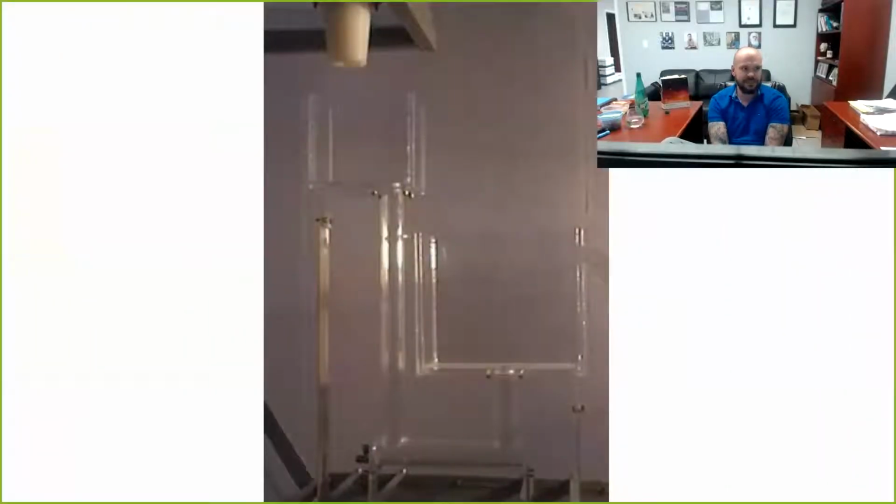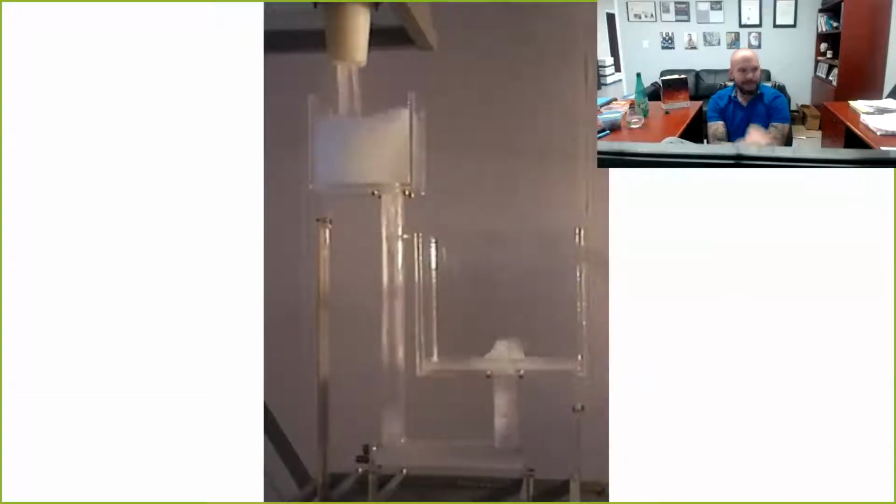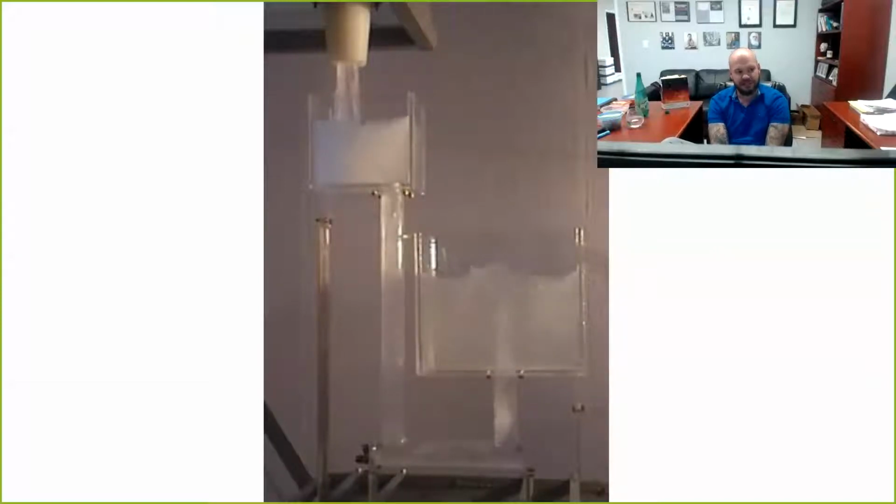And this showed between 30 and 50% of the volume of material entering the casting cavity was air. And you guys will notice that anybody who uses that preformed ceramic tube gating, this is exactly what you're doing: you're depositing between 30 and 50% air into your casting cavity. And all of that surface turbulence from the transfer, all of the air aspiration from the rough turbulence, and then all of the air bubbles are making an oxide metal soup that we want to turn into a casting.